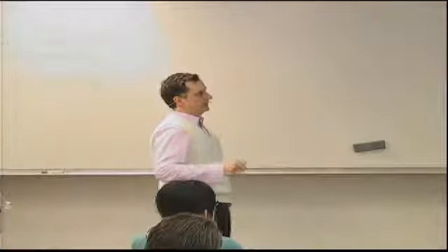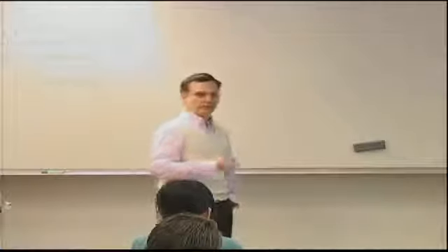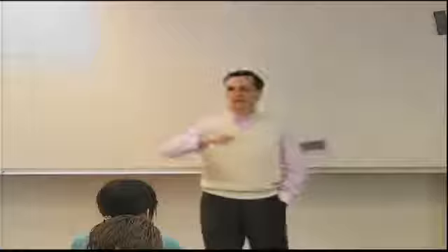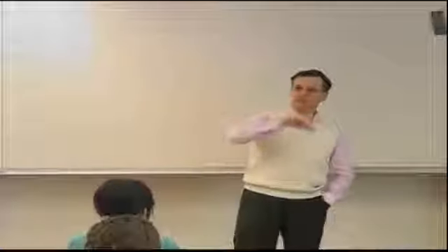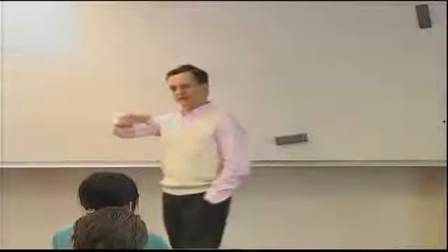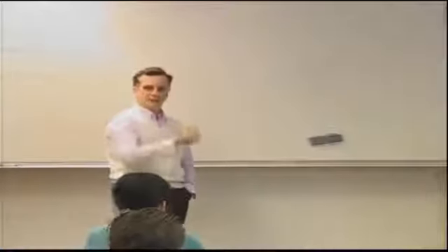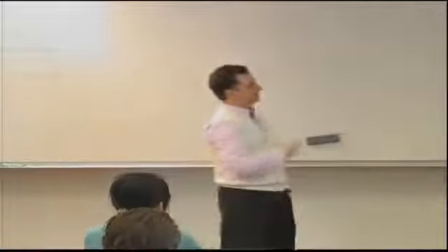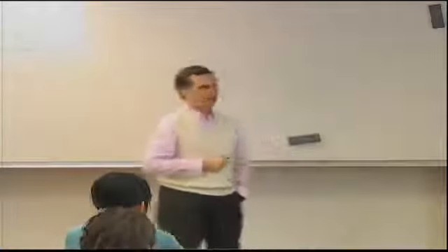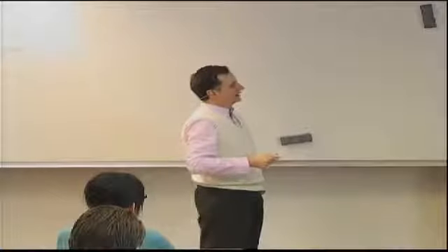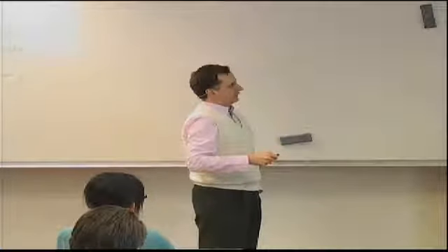And this will be the exact same plot for any x location along the plate. Yes, if you are exactly near the edges, the boundary conditions have an effect. The Saint-Venant's principle kicks in or doesn't kick in, but as long as you are a little further away, this is a very good approximation of what happens. And as you see now, the two layups have at most a 3.7% difference.